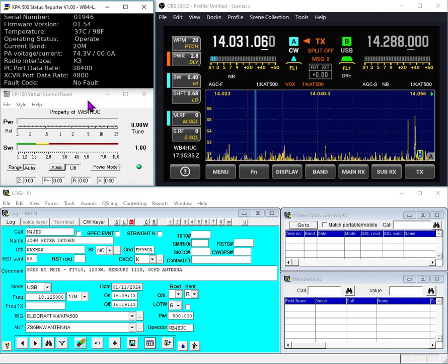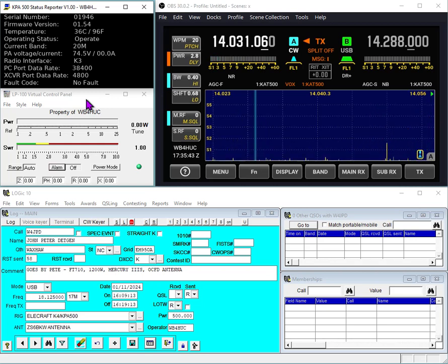So how do we do this? Well, I have 3 positions on the tuner, and I'm going to move the antenna on the tuner to position 2, which has no antenna. So it's practically just an open connector. And when I push the code key, that should cause 2 things. It should cause the amplifier keying line to be interrupted, and it should cause a fault in the amp.